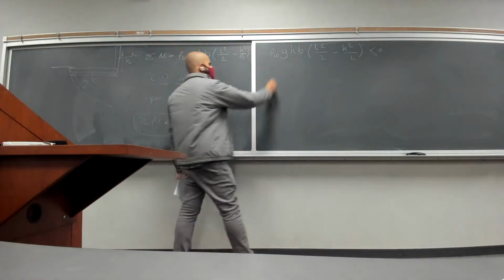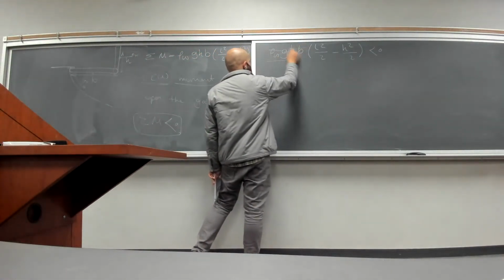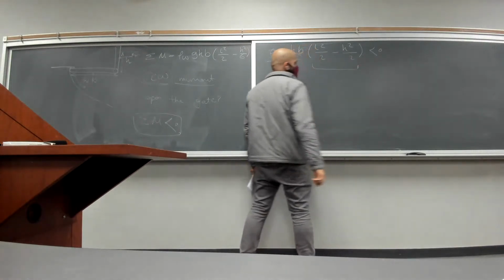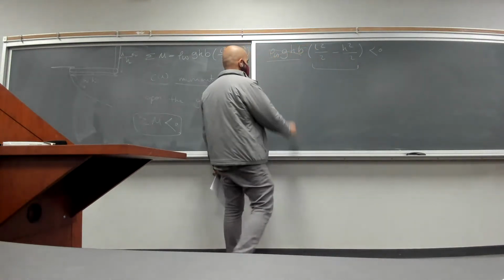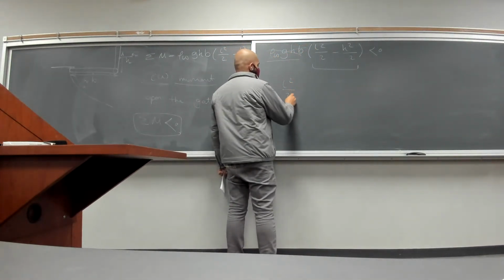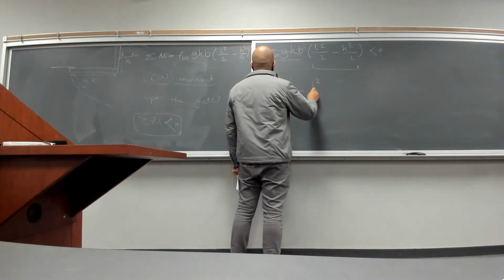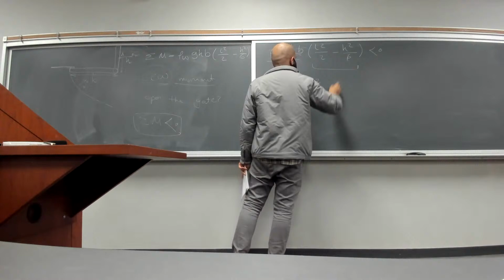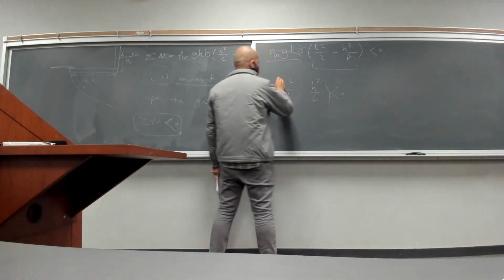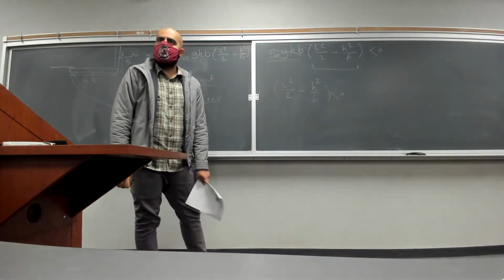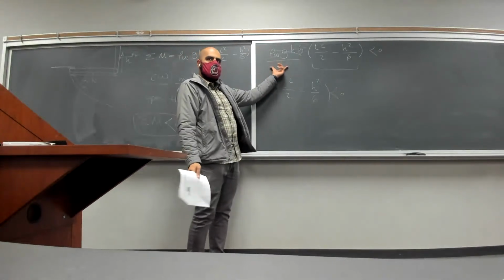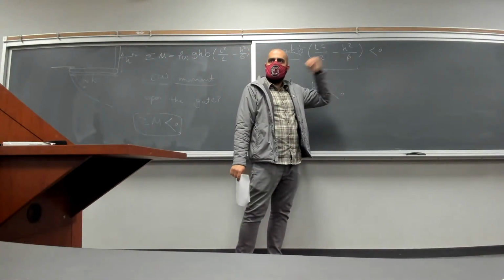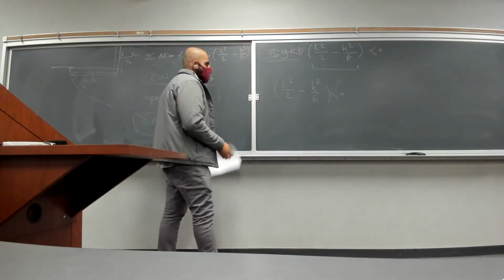These parts are always positive, they don't change. So the only part that we really can focus on is this part of the moment, L squared over 2 minus h squared over 6. Sorry. This part has to be smaller than 0, right? Because the rest of it is always positive. So positive has to be multiplied by a negative value here to become a total negative moment. Okay?